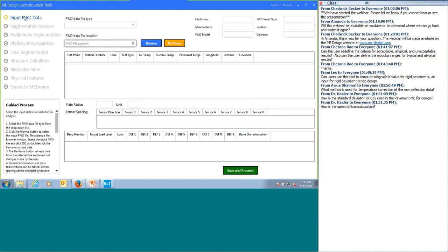The Idaho DOT measured load transfer on a flexible pavement. That's a unique feature, as many in industry have not measured the load transfer of transverse cracks in flexible pavements. I wanted to show that and discuss its use and what that might mean in terms of the pavement ME rehabilitation design.